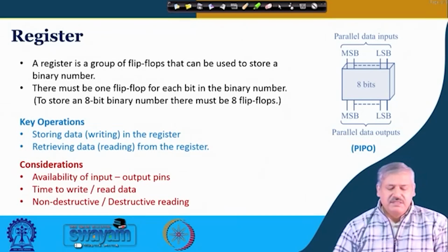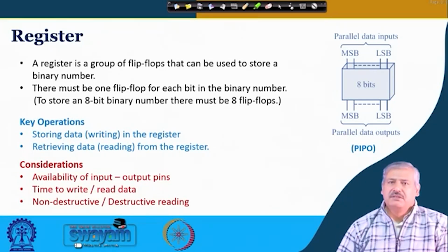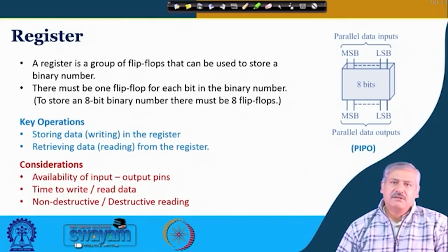Okay. So, register is a group of flip-flops that can be used to store binary data. And if we think of, say, a binary number, say 1001, if you want to store, then we need, of course, 4 flip-flops. So, the larger the number, larger the information, then we need as many number of flip-flops, and together we are doing some manipulation. So, it will be a register level manipulation that we are doing, where all the flip-flops within that particular group are addressed simultaneously, are considered simultaneously.